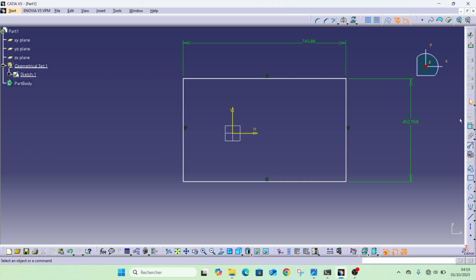We double click here, and we can do this and this directly. So we can click on this and do this and this. It will give us an angle, but it is purple, so it is a mistake. So to constrain, as I told you, we must do these two distances and this with this. So we have to click like this. It is in green color, so it is good.